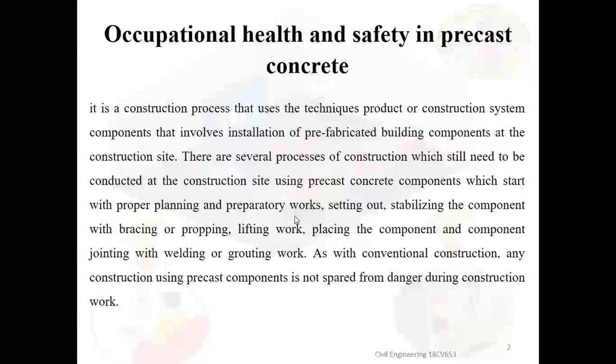So precast concreting involves the installation of prefabricated building components at the construction site, and half the construction is yet to be conducted there, with proper planning and preparation work, setting out, stabilizing the components with bracing or propping, lifting works, placing the components, and component jointing with welding or grouting work.